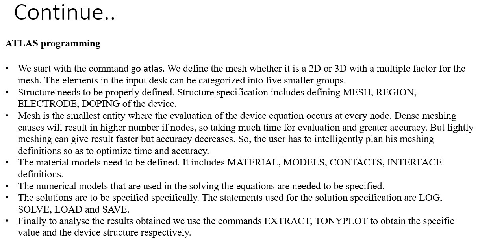Next are the models you need to add. Basic models are mobility models, band gap narrowing models, electric field dependent models, and temperature models. All the models you need to specify. You also need to specify contacts, like source, drain, and gate contacts, as well as the interface charges.